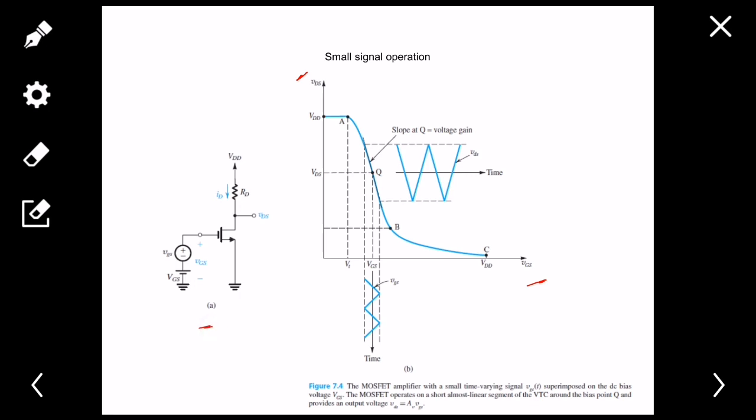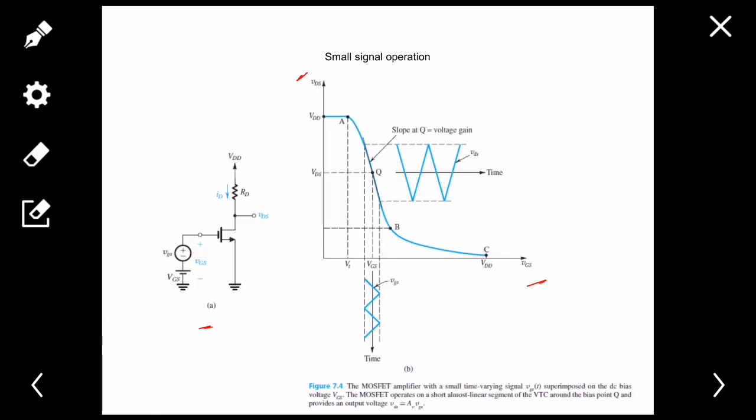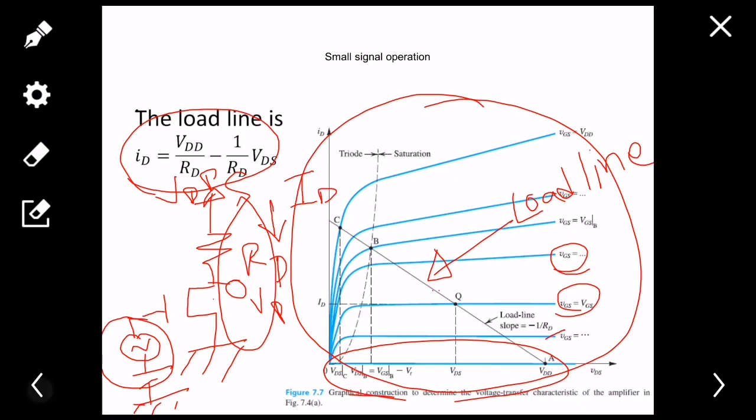And see the circuit I have drawn in the previous slide. So moving back to the previous slide again. Now see that I actually derive this VTC curve from this curve. Just see this one, you can easily understand. This particular output, that is zero current, is occurring when the gate voltage is below threshold voltage, right?